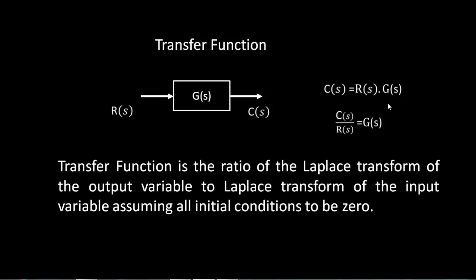Why this is important is, for example, if you are going for differential equation and converting that into Laplace, when I say dx by dt, if you make Laplace of this, apart from s or s square or s cube based on order of the differential equation, you get some more terms which are dependent on initial conditions. So if I have a differential equation like dx by dt, and if I want to convert Laplace, it is simply s, because the rest of the terminologies which are used becomes straight away 0, as we have assumed that initial conditions are 0.